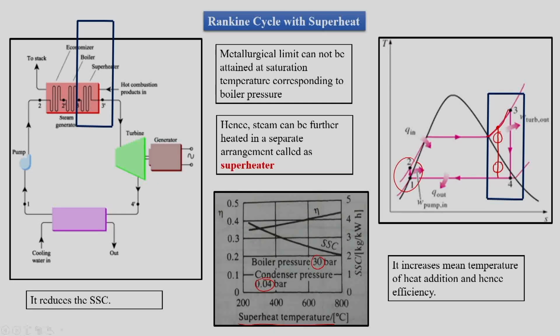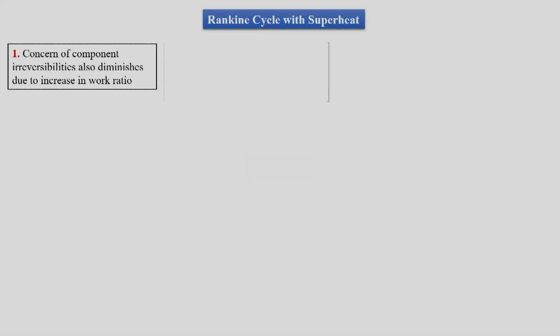So this liquid component is also flowing over the turbine, and since this liquid component is flowing over the turbine, we would have more erosion of the turbine blades. So we want less and less liquid component in the turbine blade. So for that, expected dryness fraction at the outlet of the turbine is 88%, such that most part of the turbine would have exposure to the steam or vapor only.